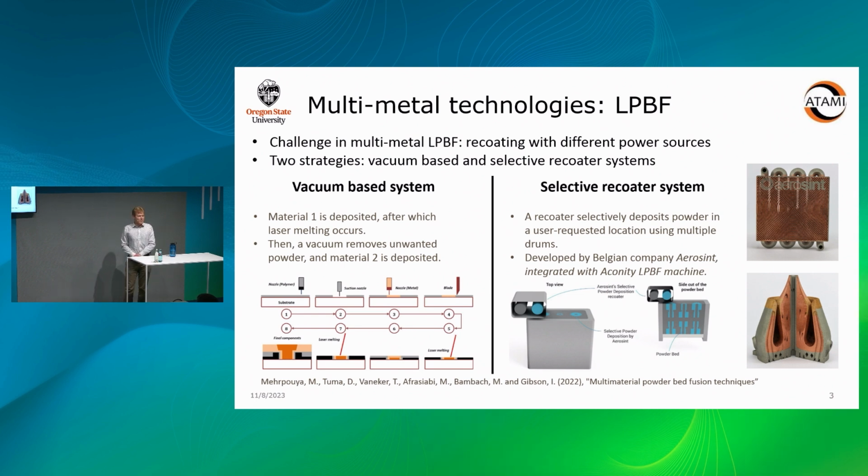So how do we go about actually making these components? We've seen a lot of powder bed fusion here. It's very progressed. We've seen that at Formnext, where there are a lot of LPBF parts being made. If we want to make this using LPBF techniques, we're going to recoat and build up in the Z direction. It's not very hard to change your material in the Z direction, so you can deposit a different material down here. But if we want to do it in plane, we're recoating a single material. Doing it in plane makes it more difficult to create a multi-material part.